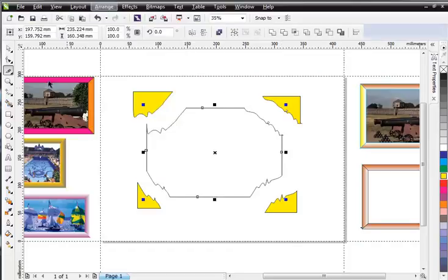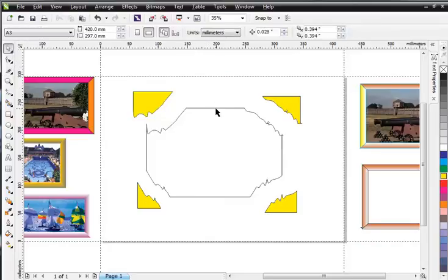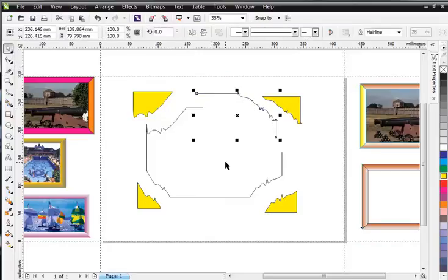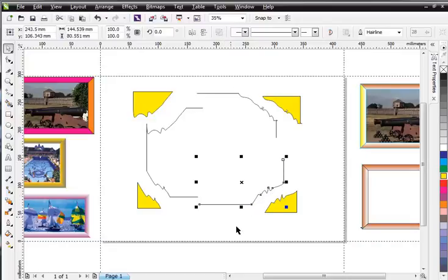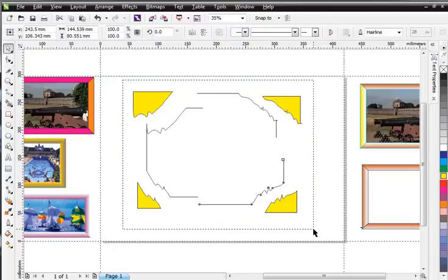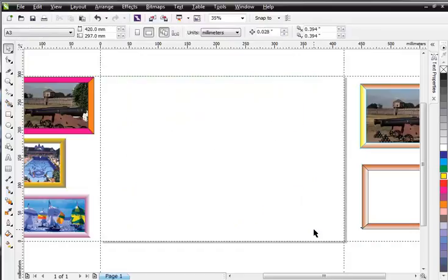We've divided the path into 4 parts. To make them separate, we need to go to the Arrange menu and click on Break Curve Apart. We can now switch to Pick tool and move these paths separately. So this is how the knife tool works. Select all these elements and delete them. Let's move to our main subject.